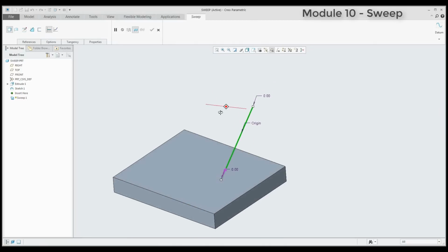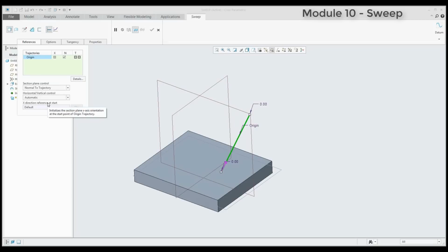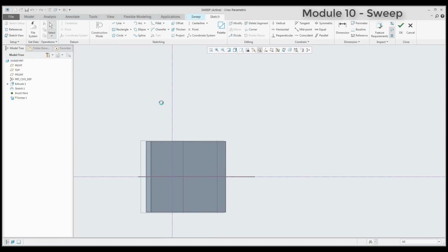I would like to try to explain to you how to use the reference orientation. You can see here that there are a lot of controls, buttons and possibilities for how to orient the sweep feature. If you work with sweep, it's necessary to select an edge or curve, and then you need to select the section directly in the feature.